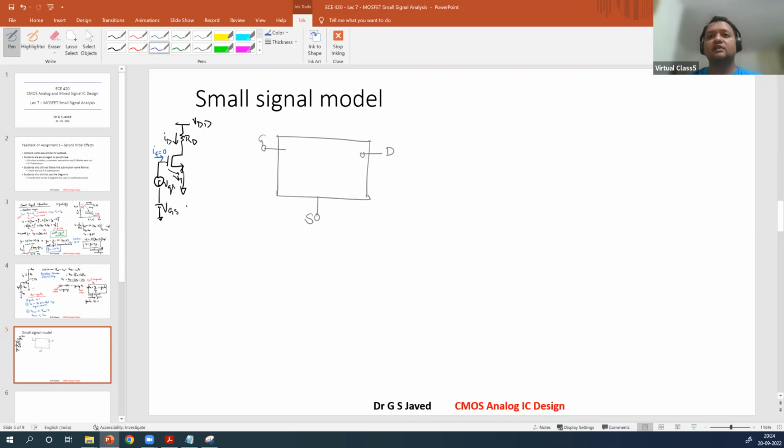Now, why have I done this? Because this is called a common source configuration of using a transistor. What does this mean? The source is common between the input and the output. Here, what is your output? Your output V0. This is your input V in. So what is the common? Input is measured to the ground from VGS.